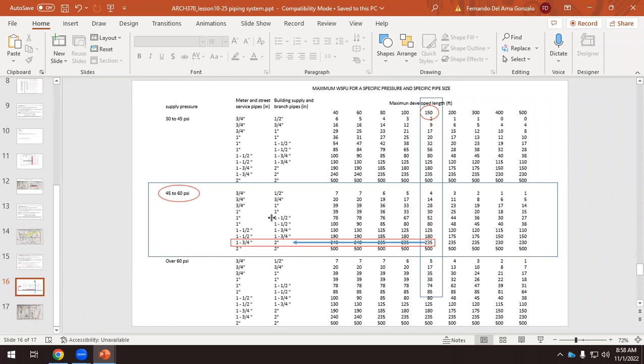Okay, this is it. I'm not going to do the hot water, and the hot water is going to be less than 2 inches because we have fewer fixture units. We only have the 4 sinks in each restroom. Okay, so we have 6 times 4. So probably the main duct for the hot water supply will be much smaller than this one.